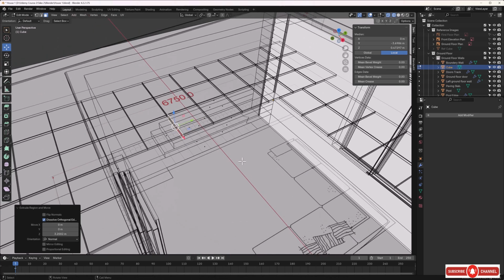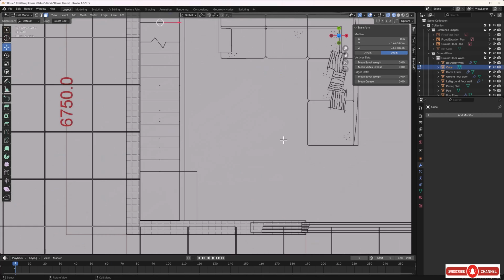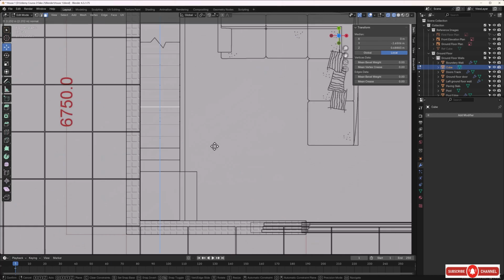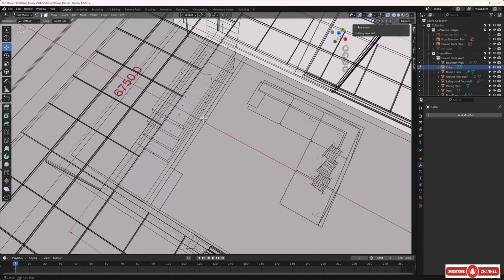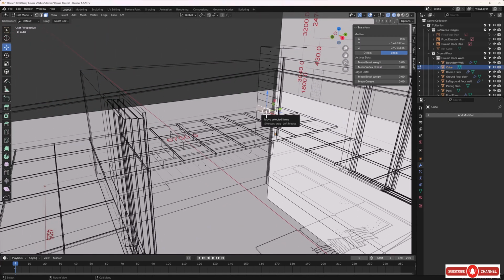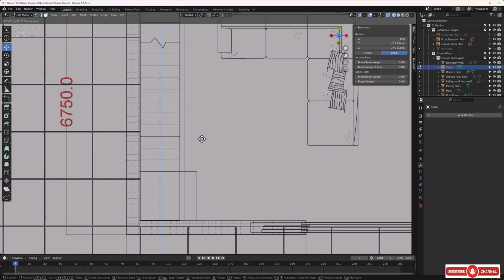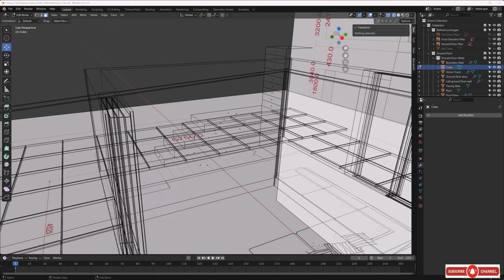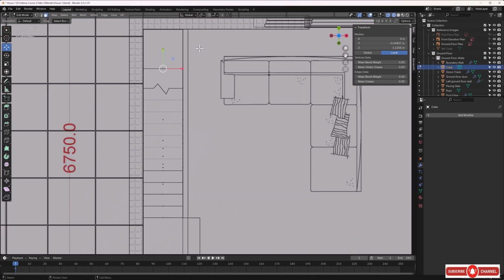And just keep on repeating the process all the way to the top. Remembering, of course, to just click on dissolve orthogonal edges. Okay, so let's carry on doing this. So I'll press 7, and I'll press E, and just keep on bringing these over, and dissolve orthogonal edges.